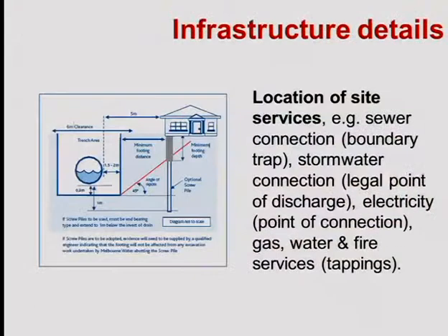Okay. Infrastructure details, that's where all the services are. Why do we need to know that? Because when you build a building, it generates load. And that load is generally distributed at a 45-degree angle from the outer point of the footing system.